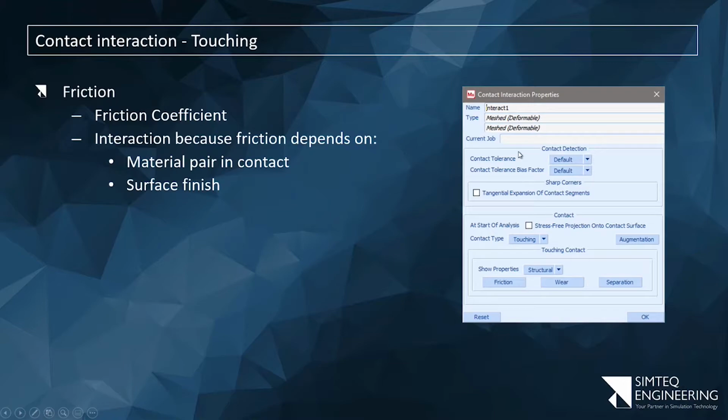So the interaction, because I'm going to reuse it, let's say I've got a model with different materials: steel, aluminium, plastic, I don't care. Then I specify an interaction, and I can give it a name that says this is specific to touching between steel and aluminium parts, and you fill in all the properties.